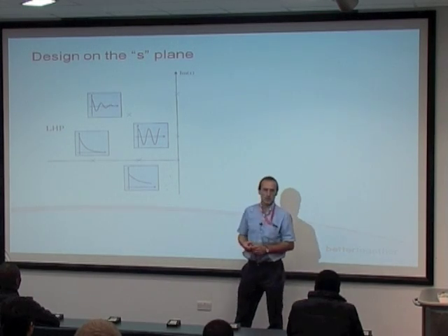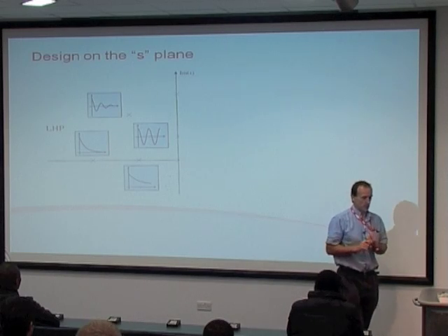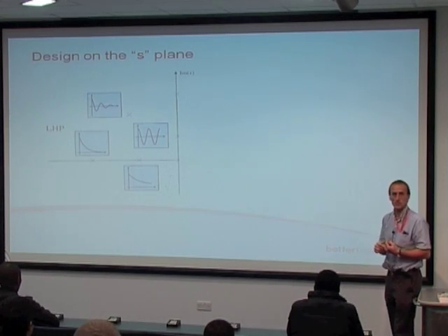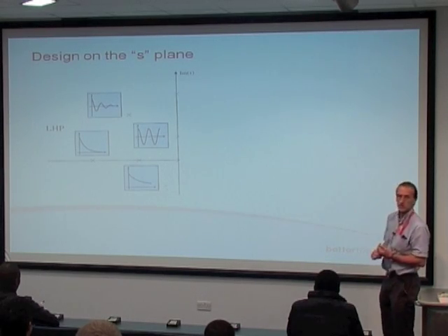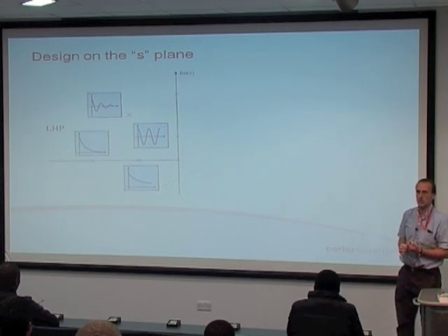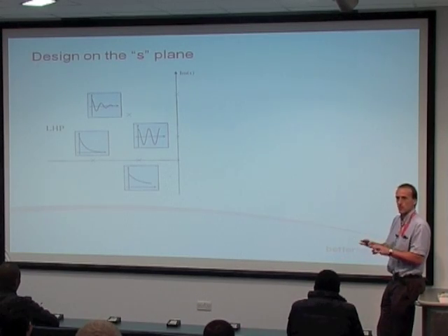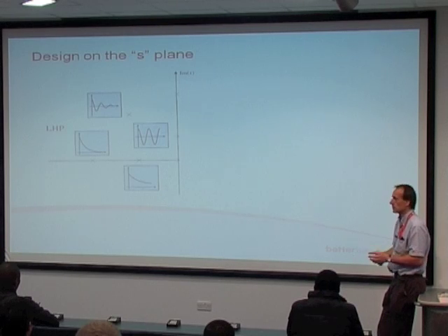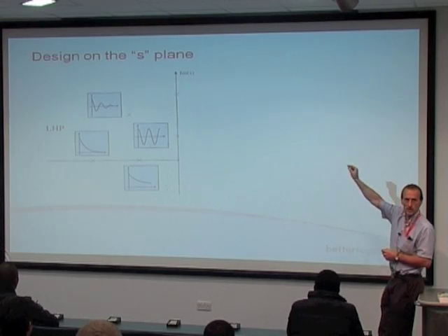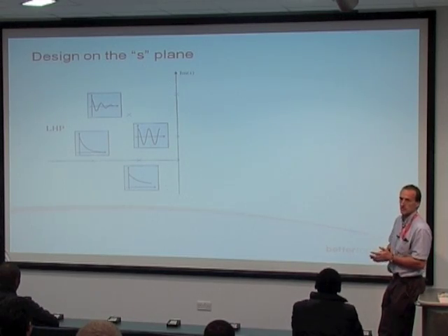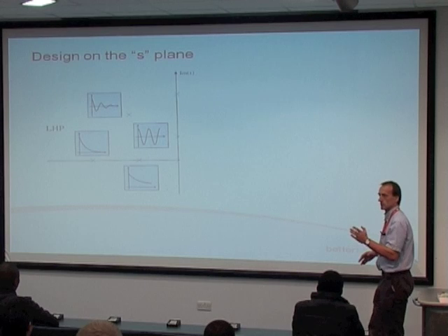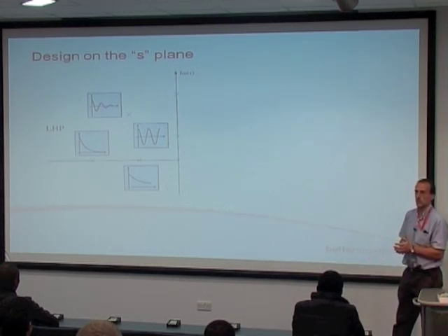The imaginary part tells me about the frequency of oscillation of that system. Okay. So the further up the imaginary axis I go, the faster the oscillation. It's related to omega n. Okay. And if you have a look at what happens when you factorize a typical second order quadratic, omega n is the number that determines the value of that imaginary part of the pole. It's not equal to the imaginary part, but it's what determines it.